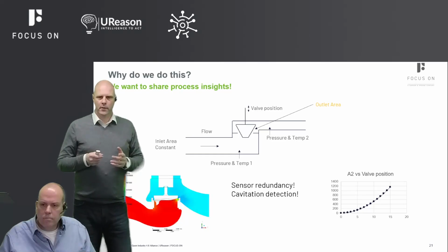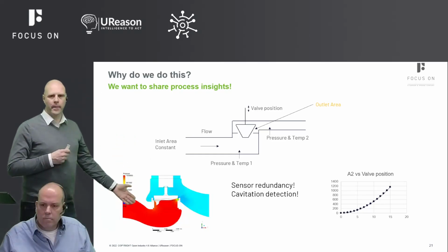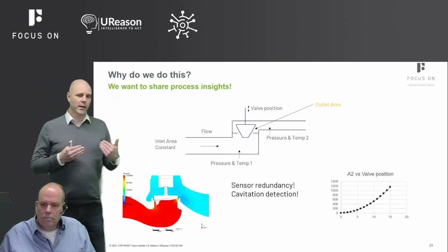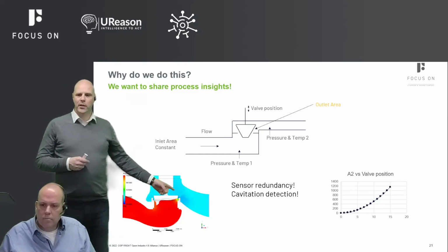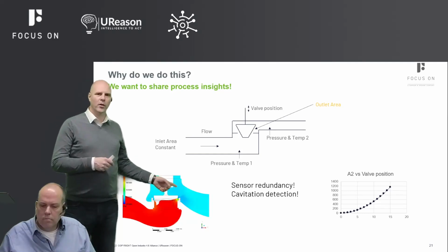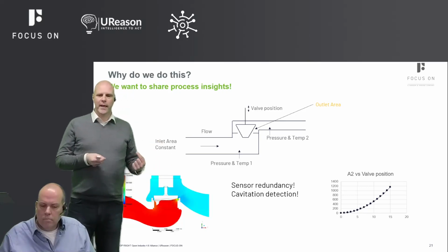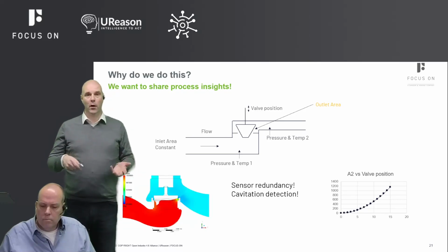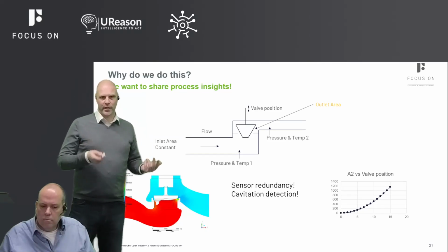It's not just that. So this is looking at the mechanical workings of the device. But when we know a little bit more about the process, what's happening there, so we have the speed of sound of the ultrasonic transducers, we have the signal to noise ratio, we have gain values, and we've got all the other information there, we can actually calculate and show cavitation. And then it becomes a little bit more interesting for the process engineers and the process owners to see, hey, how well is my device doing? Is it cavitating? Is it wearing out? And why is it cavitating? Are my process conditions correct? So we get a lot more insight in the process, and we want to share that information.